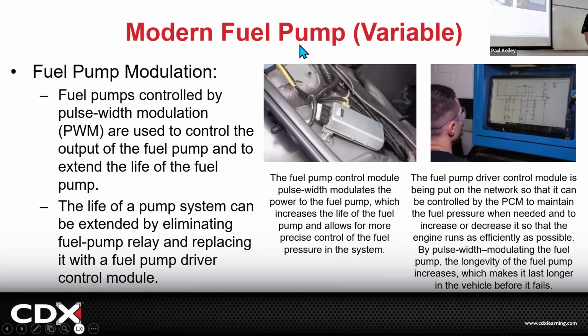A modern fuel pump is going to be variable. They'll call that fuel pump modulation. So fuel pump modulation means we'll turn it on, we'll turn it off, we'll speed it up, we'll slow it down, right? So when we were looking at that old picture, the first fuel pump was pumping as much as it could, all the way up to the engine and all the way in the return. That was hard on it.